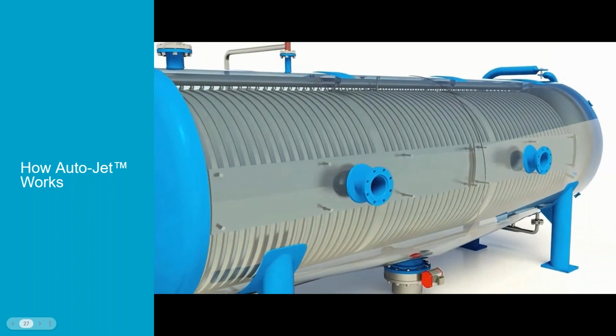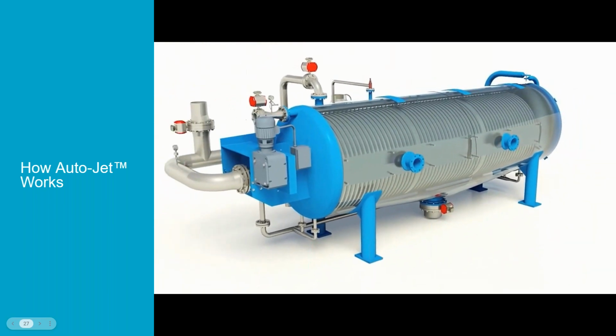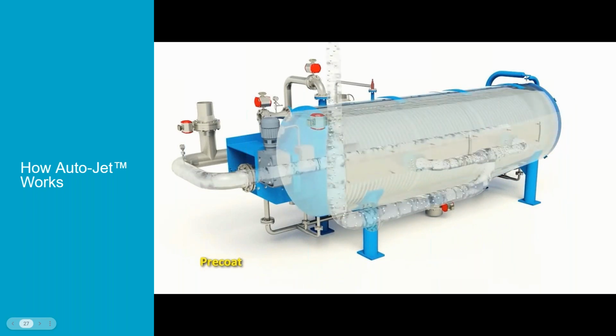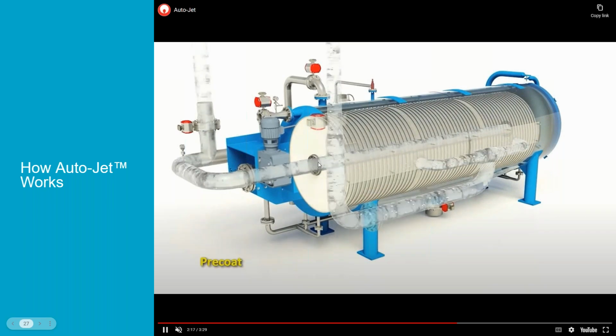Now we'll take a look at a full sequence of the filter, how it operates. So the first step is the Precoat cycle. For this, the vessel is filled with the Precoat solution and is recirculated until you get a nice thin layer of Precoat on each of the leaves.